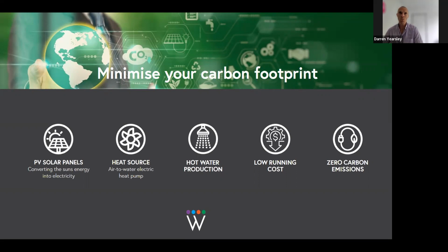So what we try and do is create a model for how the system needs to operate, how much water we need to produce to shower everybody in the building. Once we have that information, we work out how much water I need to supply, how much water I need to store, what rate I need to recover it using my high temperature heat pump, and then that drives the size of the solar PV array. And once you get these things in the right proportion, the storage versus the recovery versus the solar array, the capital efficiency of the system comes right down.